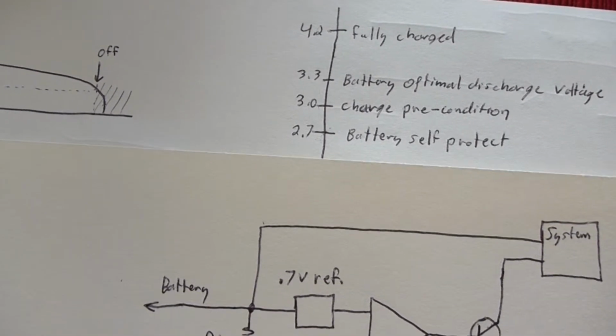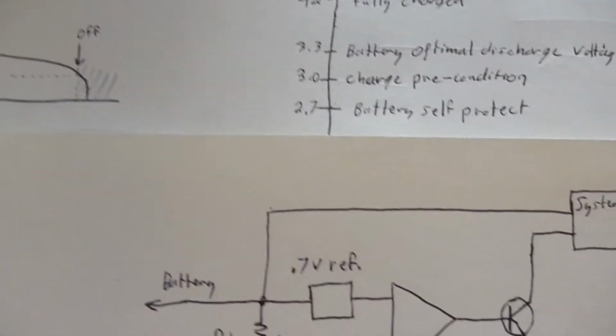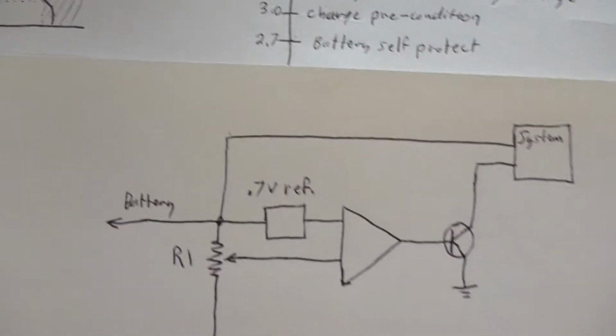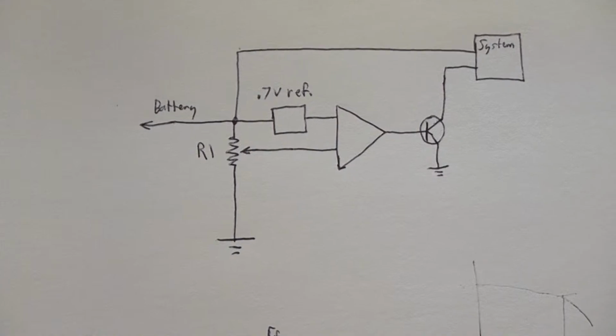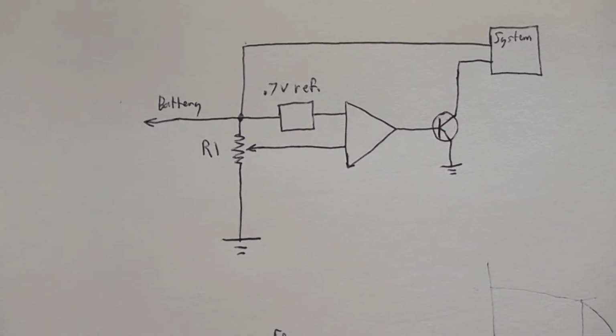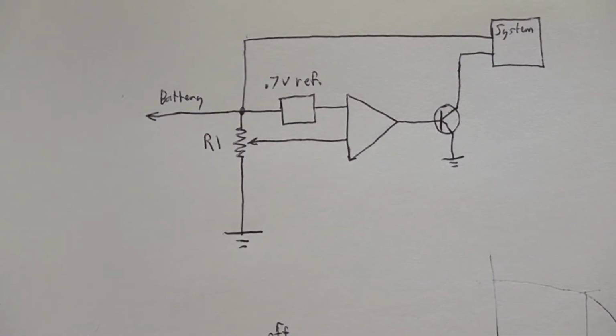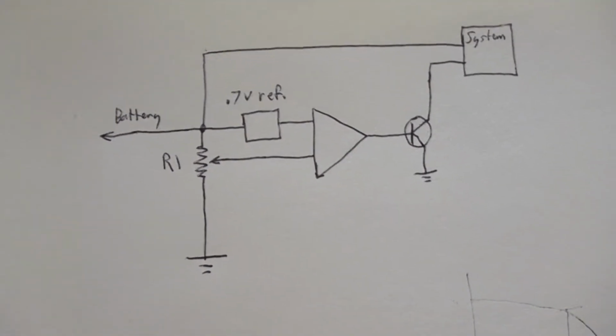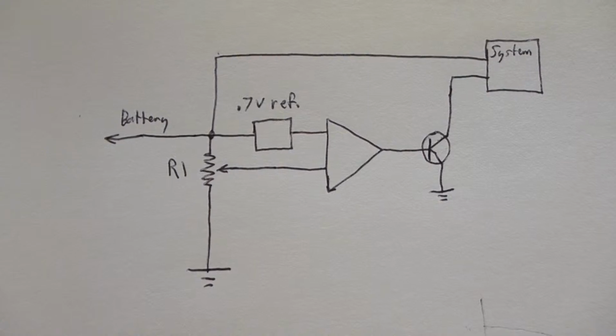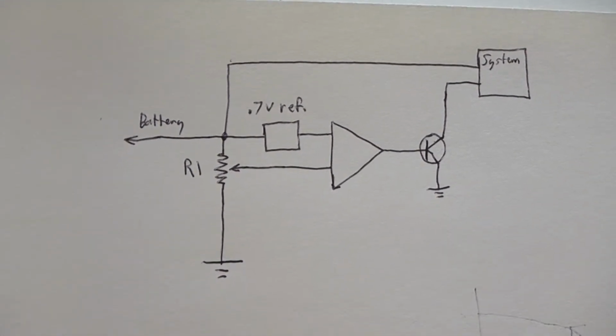If you get batteries directly from other manufacturers, particularly some of the cheaper ones from places like Deal Extreme, those batteries are great and they're fine, but they don't have protection circuitry in them, so they will discharge all the way, and then you hook them up to a charger that's also not very high quality, and the battery can definitely explode.